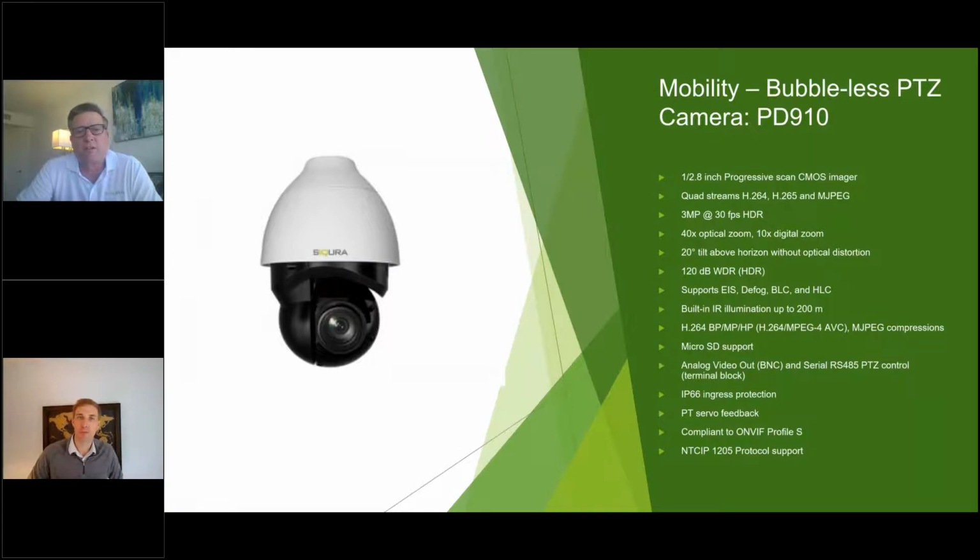The benefit of not having a dome is that it is covered. You can see the lens on the front of the camera there. That is coated with a nanoglass type surface, so water, dirt, insects, whatever might come across it is not going to stick to it as easily as it would sometimes on a dome. Oftentimes these cameras are mounted pretty high in an intersection or near an intersection or other places, to get a good field of view. So maintaining them, having to go up and clean them, is time consuming and costly. This probably requires half as much maintenance, or even less, depending on the weather and other things in the area.